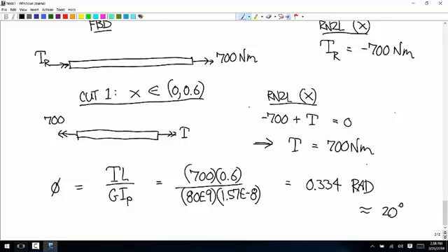That's not a super huge torque, but that's a bar that's almost a meter long. The longer this thing gets, the bigger that angle of twist could be. If you had something that was 6 miles long and you applied a pretty small torque to the end, you could still get that thing to go all the way around multiple times and still never have very big strains. Okay.